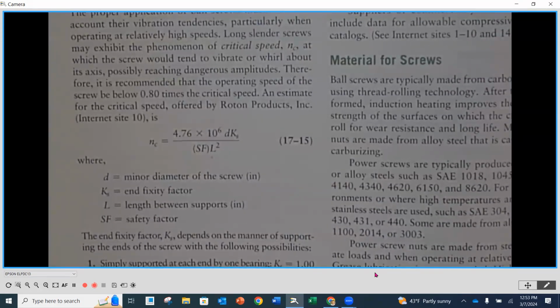I don't know if there's a way to do that for those. Probably not. You just have to get larger, probably. What you go to next is rack drive, so rack and pinion. You have a really long travel, you go past ball screw ranges, you mount the rack to the bed of a machine, and then you'll have a servo motor with a gear on it, so the little gear spins you back and forth.